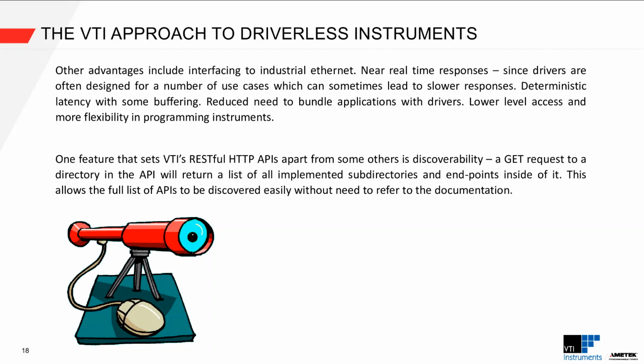This means that you can discover every command possible that you can send to the instrument just by sending it a simple GET. So while you have a manual, and that's obviously important to know what it is that you want to do, by using this GET command, you know exactly what commands are available to be sent. It works as a reminder when you're writing your application, but it also ensures that you're not sending an invalid command to the instrument.